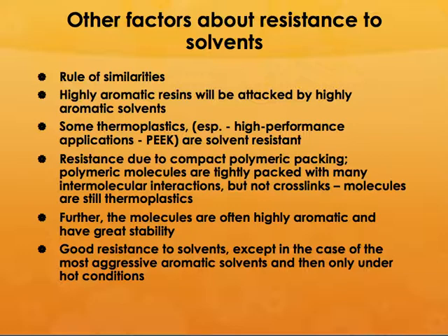If the molecules are aromatic in nature, they have extremely good stability. But if they are not, they are not going to stand, and I would say that the molecules can penetrate between the fiber layers and attack the fiber matrix bonding.